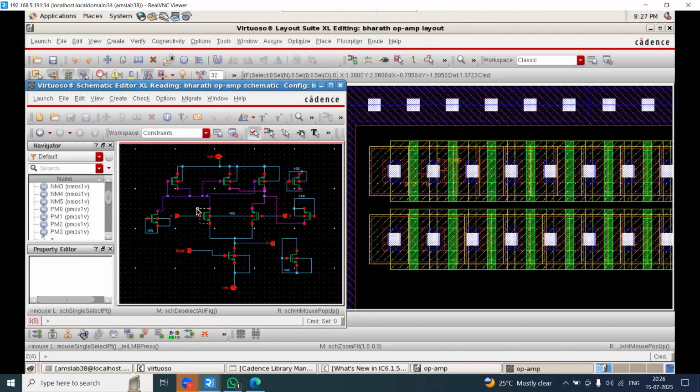Formally, sometimes people will ask you to make a full signal dummy, but full signal dummies will create more leakage within the device fabrication. So my internal team suggested never ever to use full signal dummies in the corner in the layout. Try to use stack dummies. That is one more option they have given. Different fabs will have different things. In 3 nanometer FinFET technology we won't have the dummy concept. In FinFETs we will be using filler cells.